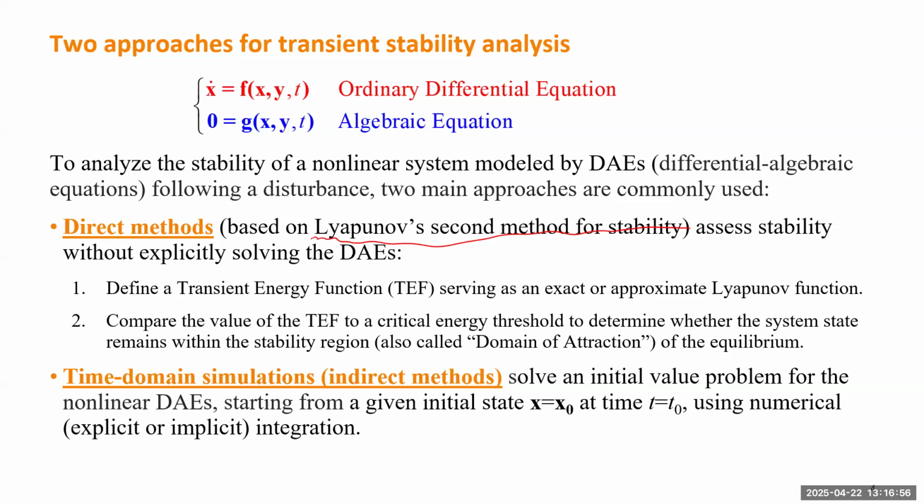Indirect methods are typically time domain simulations. We need to solve an initial value problem for the set of DAEs, starting from an initial state at a certain time. Basically, you need to utilize a numerical method to solve the DAEs for the system response at any desired time. The simulation needs to be done for a long enough period until you can clearly tell the system to be